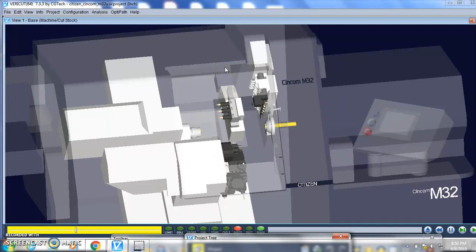When I say multi-channel, it's multiple programs running at the same time. These programs work either independently or depend on each other. They run in a way of interfacing with each other. They will wait for each other. They will sync with each other. They will have a synchronized effect on the complete programming process itself. So please go back and look at the video about the CNC multi-axis program, machine setup and program.